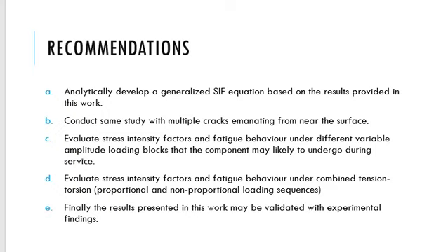Okay, the recommendations are: first, analytically develop a generalized stress intensity factor equation based on the results provided in this work. Conduct the same study with multiple cracks emanating from near the surface. Evaluate stress intensity factor and fatigue behavior under different variable amplitude loading blocks that the component may likely undergo during service. Evaluate stress intensity factor and fatigue behavior under combined torsion, proportional and non-proportional loading sequences. And finally, the results presented in this work may be validated with experimental findings.